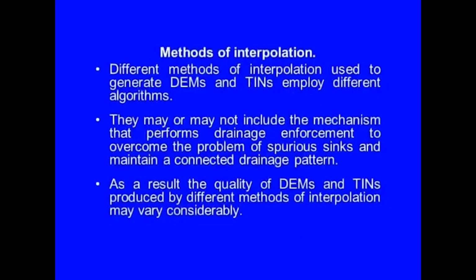Method of interpolation. Different methods of interpolation used to generate DEMs and TINs employ different algorithms. They may or may not include the mechanism that performs drainage enforcement to overcome the problem of spurious sinks and maintain a connected drainage pattern. As a result, the quality of the DEMs and the TINs produced by different methods of interpolation may vary considerably.